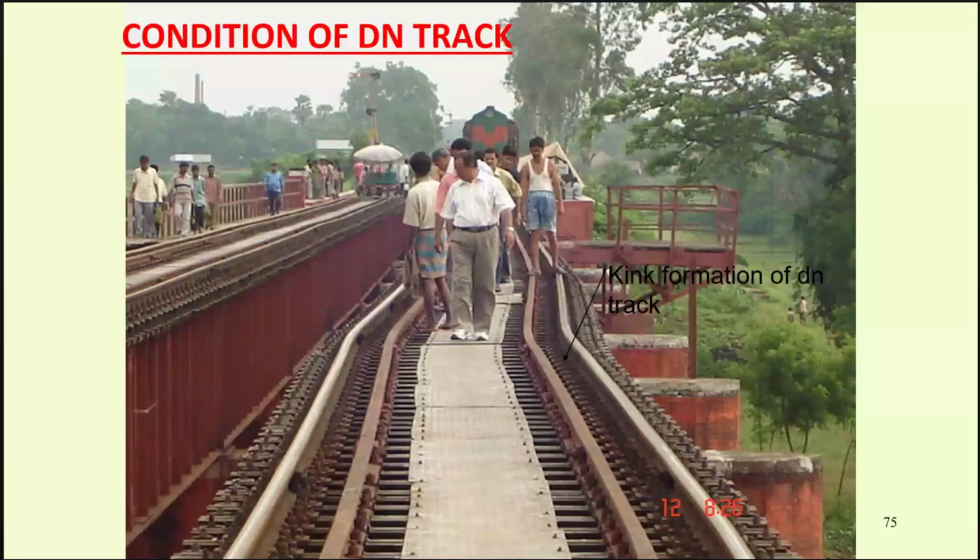This type of misalignment cannot be taken care of easily. You need to put in a lot of effort: settle or correct your pier and abutment, then use mechanical means to restore the alignment.